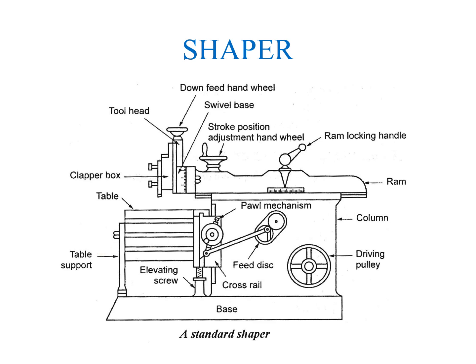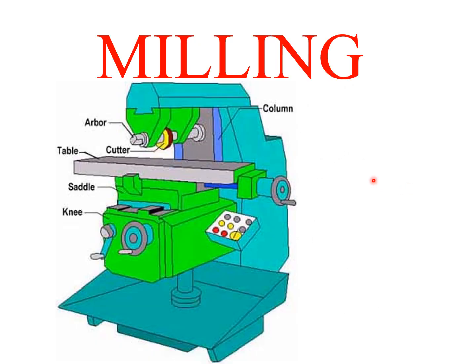Then milling machine. In general, milling is a cutting process that uses a milling cutter to remove material from the surface of a workpiece. The milling cutter is a rotary cutting tool, often with multiple cutting edges. As opposed to drilling, where the tool is advanced along its rotation axis, the cutter in milling is usually moved perpendicular to its axis so that cutting occurs on the circumference of the cutter.